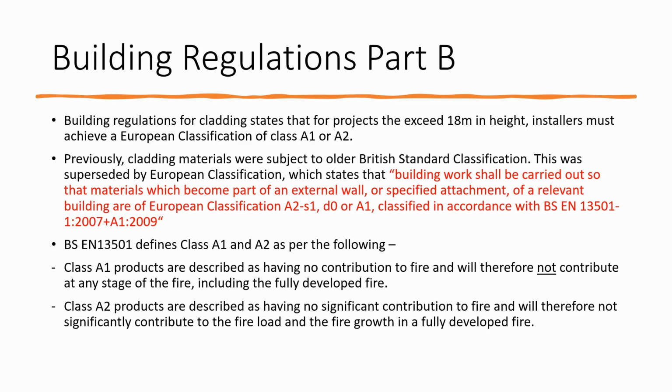This was superseded by the European classification, which states that building work shall be carried out so that materials which become part of an external wall or specified attachment of a relevant building are of a European classification A2, S1, D0 or A1, classified in accordance with the British Standard EN 13501-1:2007 and A1:2009.